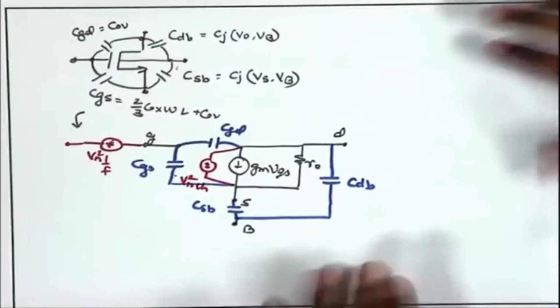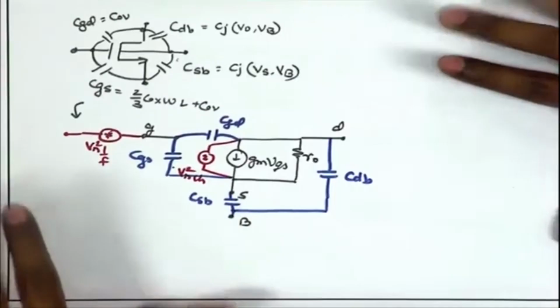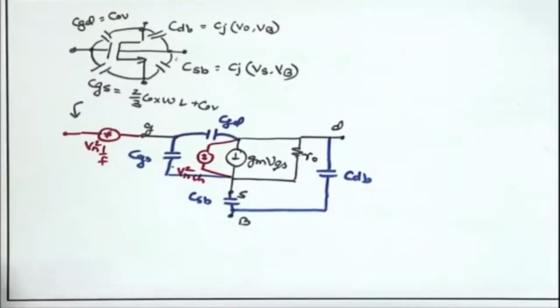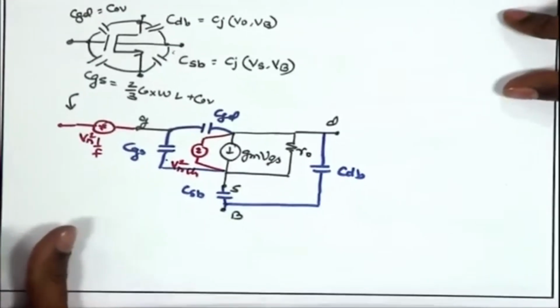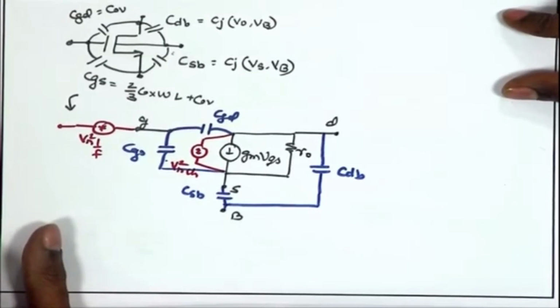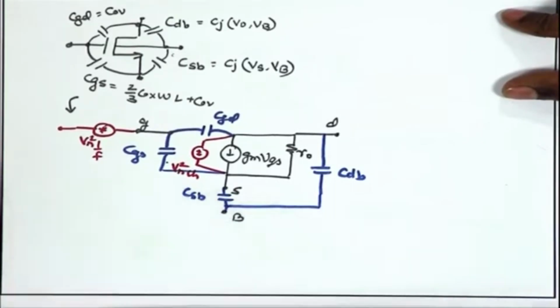Welcome back, and now we have the basic recipe at device level ready. We have gone to the DC characteristics of the MOSFET. From there we have understood how to arrive at the small signal parameters of the MOSFET at lower frequency. Then we have looked into the parasitic capacitances, their physical origin, how they affect the signal propagation through the device, and finally we have added the noise sources to the device, looking at their physical origin and also incorporating them in the small signal model.